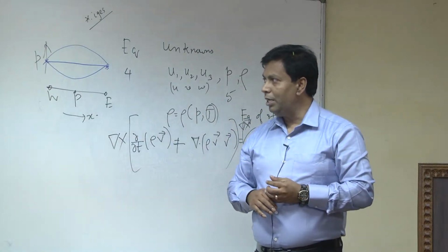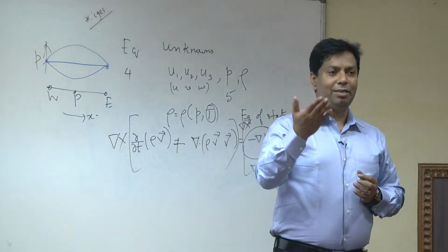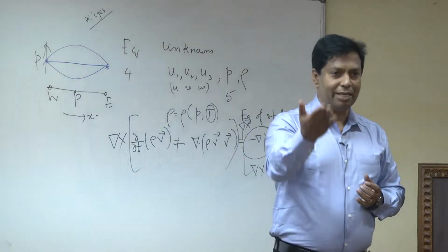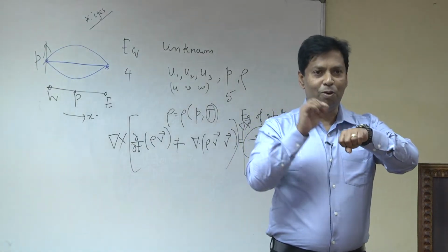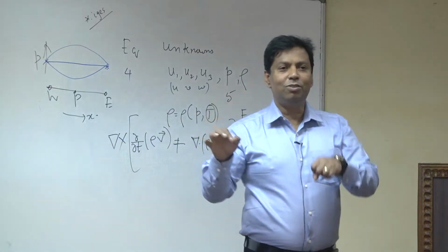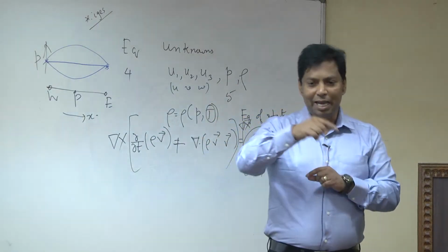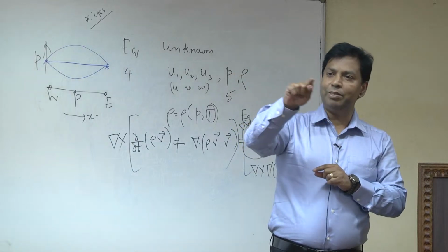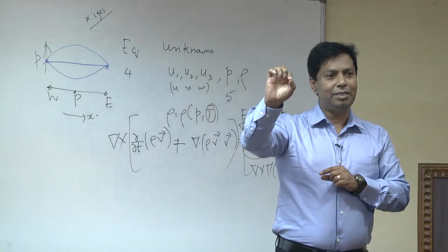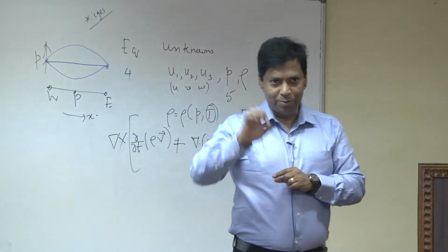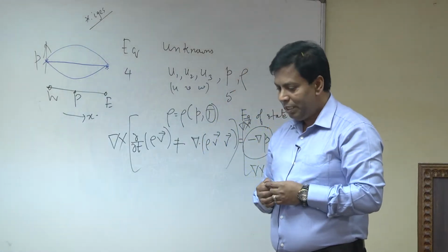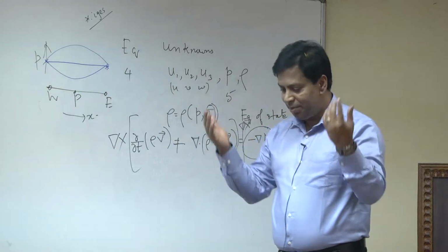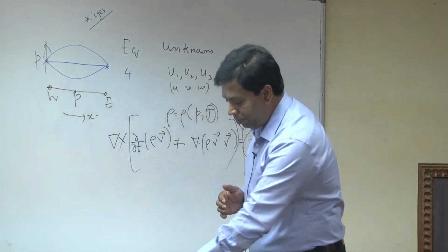So, he told me to simulate 10 iterations and see how much real time it takes for a single processor, then for double processors, and draw a curve, and when the curve converges, take that one. That is how many processors you need. That is very important. It is not always good to use the maximum number of CPUs.